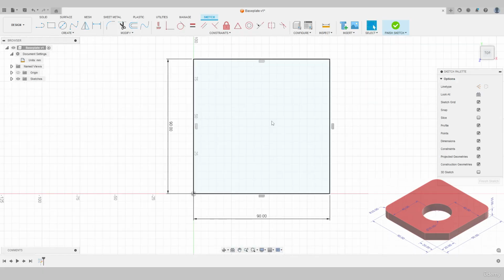Now let's go ahead and add in this chamfer. We've got a 45-degree chamfer at 20 mil. To do this, let's come under the Sketch tab again, and in this case, we're going to select the Line tool. I'm going to put the chamfer on this corner here. I'm just going to left click on the vertical at any position, it doesn't matter for now, and then left click also any position on the horizontal. Then we'll want to apply a dimension between this endpoint and the origin at 20 mil, and likewise for this endpoint. So let's come up to Sketch Dimension, or shortcut D on the keyboard, select the endpoint of our line, select the origin, and left click once.